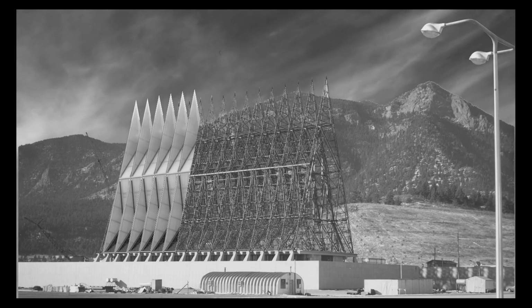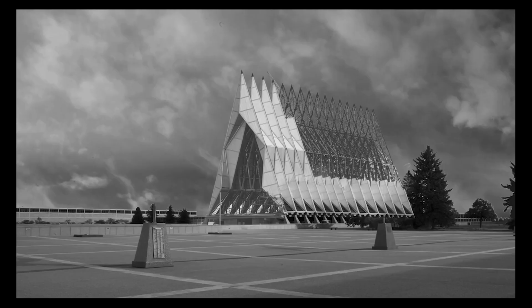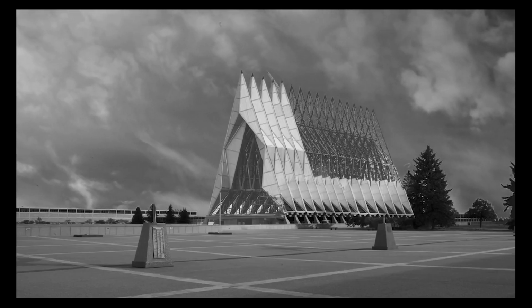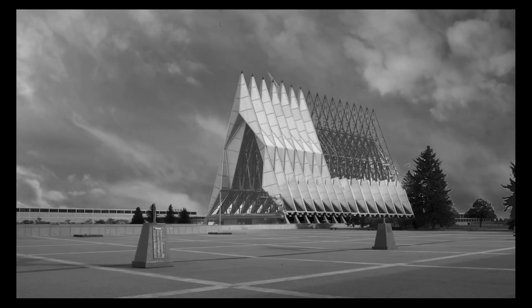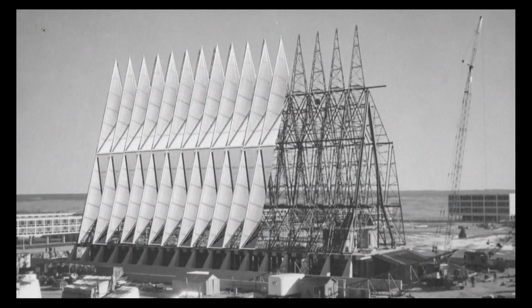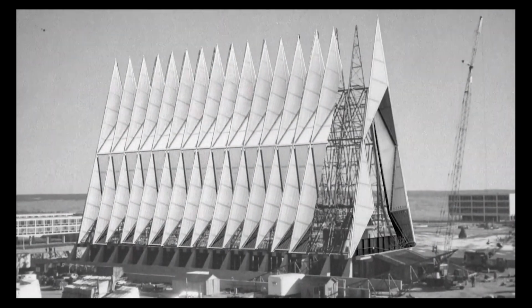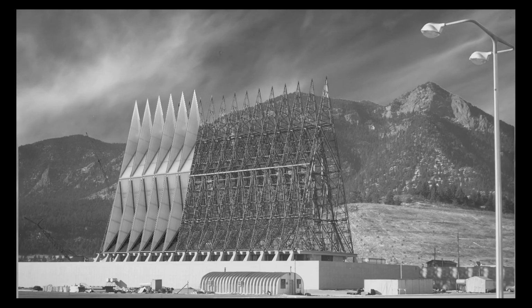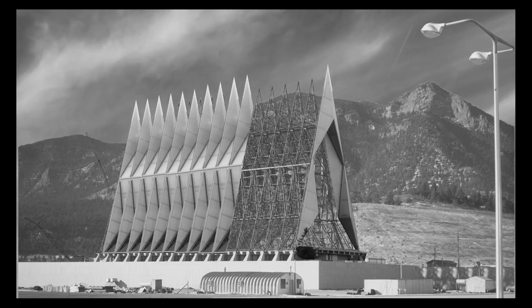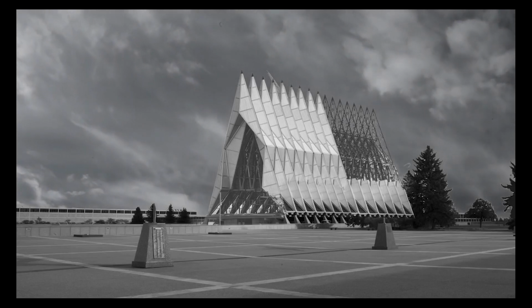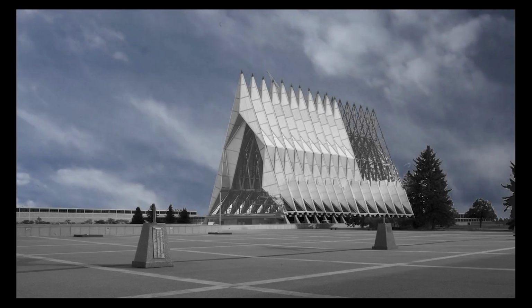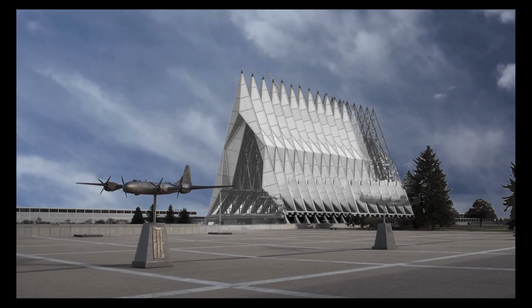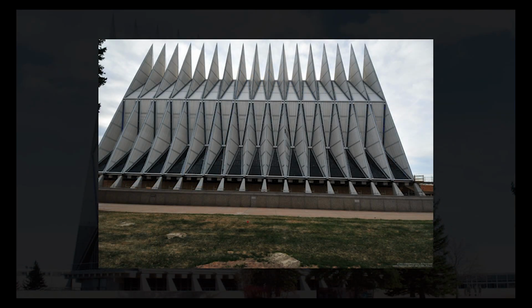You guys might wonder if the folded aluminum plates would have any structural effects on the chapel. Well, they do. In folding systems like the one employed in the Cadet Chapel, the distribution of internal forces is crucial for maintaining structural integrity. These forces primarily travel along the folded edges, where localized accumulations of stress can occur. However, through a process of load transmission to the sides, the overall load is dispersed, ensuring balanced force distribution throughout